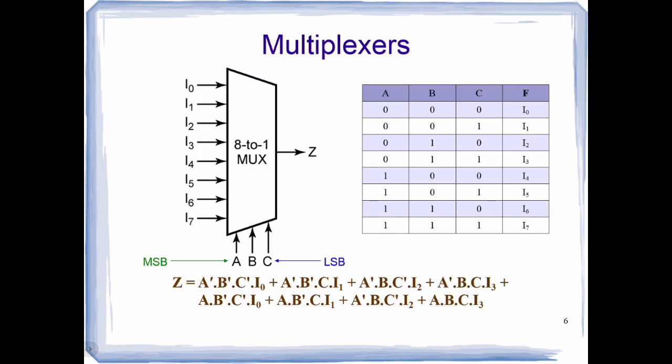Next, we talk about 8:1 multiplexer. The figure shows an 8:1 multiplexer. There are 8 input lines, 1 output line, and 3 selector lines as shown in the function table, and selection of a particular input line is controlled by the 3 selection lines.